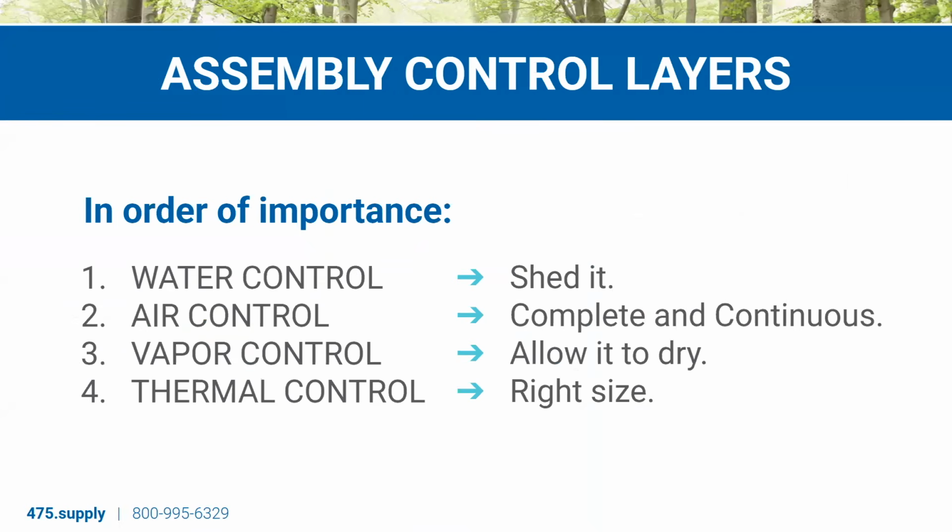For climate zones 1 through 3 and A in particular, humid climates, we want an exterior class 3 vapor retarder, i.e. between 1 and 10 perms. That would be the Solitex Mento membrane over OSB. We're pairing the high permeability membrane with the lower perm sheathing, or it could be the Adhero membrane over plywood. And then for climate zones 4 and up, we're relying on the Intello membrane on the interior, the humidity dependent vapor retarder that's changing its vapor permeability.